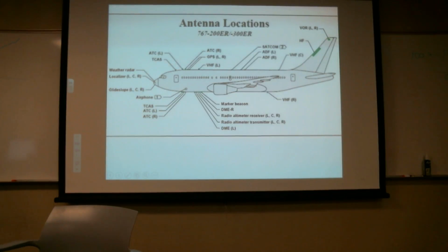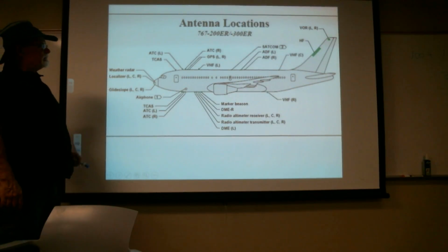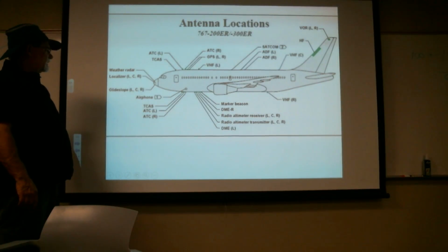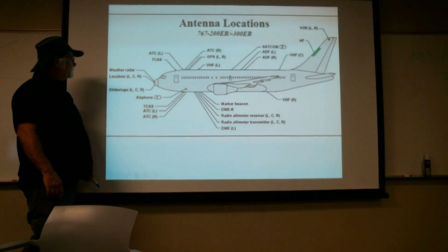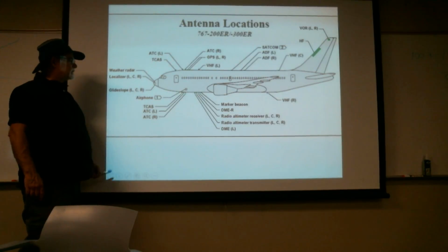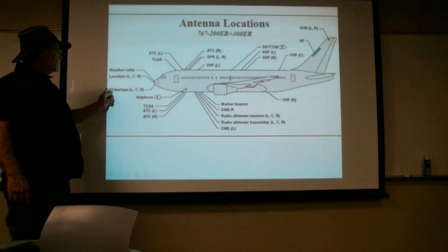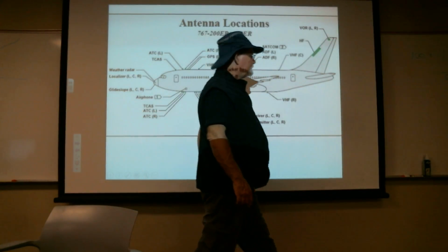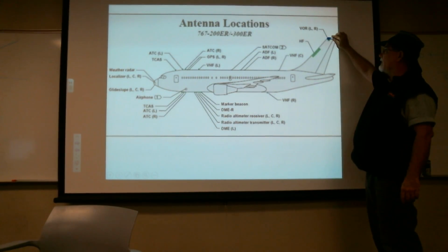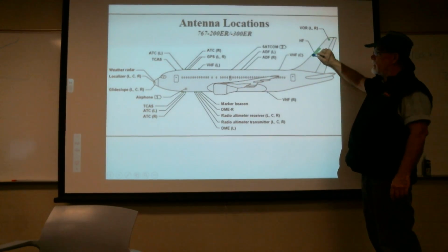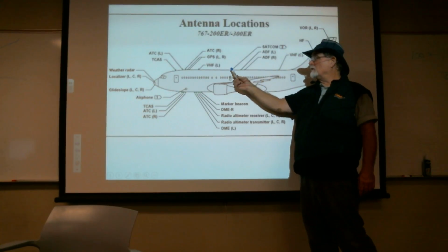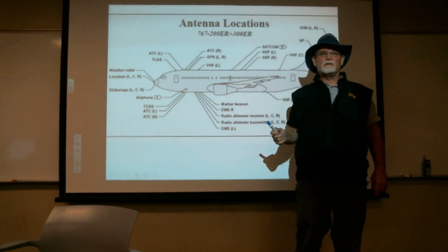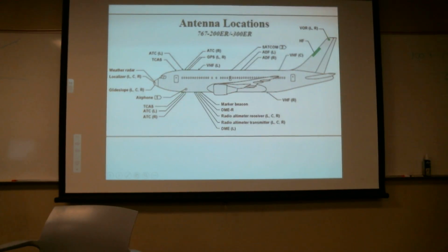This one shows a very big bird. Let's see, this is a 767 extended range. And it's got all kinds of little whistles and bells sticking out around there. GPS, several GPSs, TCAS, VHF, long range, or your left and right one. Second TCAS. That's probably a port. Some of the navigational stuff's going to be in the nose. Okay, weather radar, that's kind of nice up there. Again, also more navigational data up here. High frequency transmission for long range stuff if you need it. You might have SATCOM, some of the Southwest where they got the little cell phone biscuits put on top. That's actually satellite antenna array.